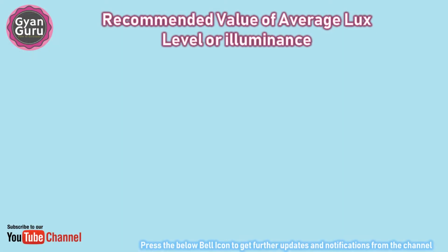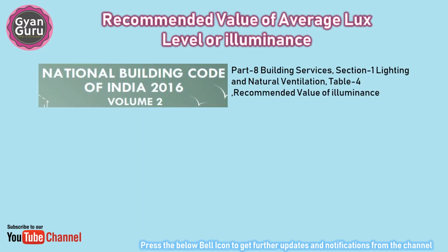For the recommended value of average lux level or illuminance, one can refer to the National Building Code 2016, Part 8 Building Services, Section 1 Lighting and Natural Ventilation. There is a Table 4, named Recommended Value of Illuminance. In that table, you will find the recommended value of illuminance for various applications.